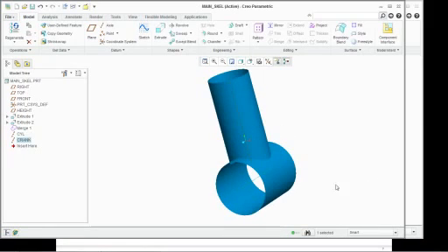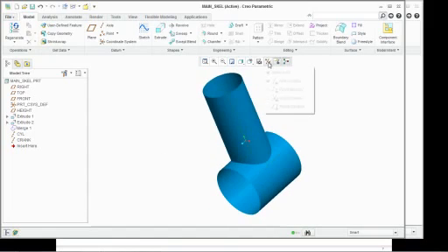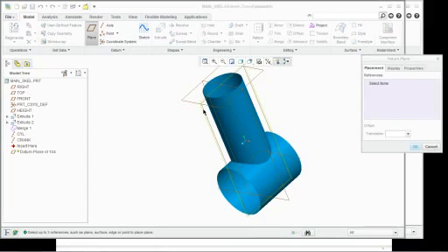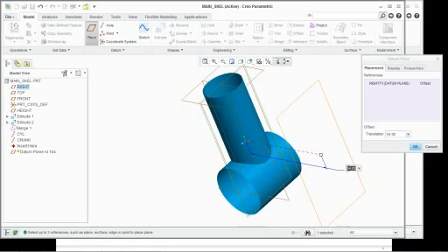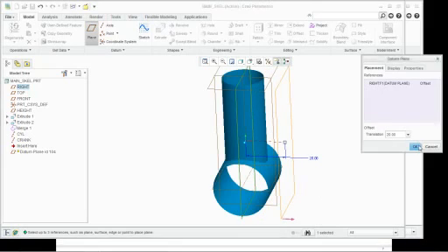And then we're going to come in and create from the top plane here. We're going to select our top plane. Or I guess, actually, I'm sorry. I need to turn my planes on. So you can see I'm going to offset some planes first. First I'm going to offset a plane off of here. We want that to be offset 10. And make that 20, make it spaced out just a little more.